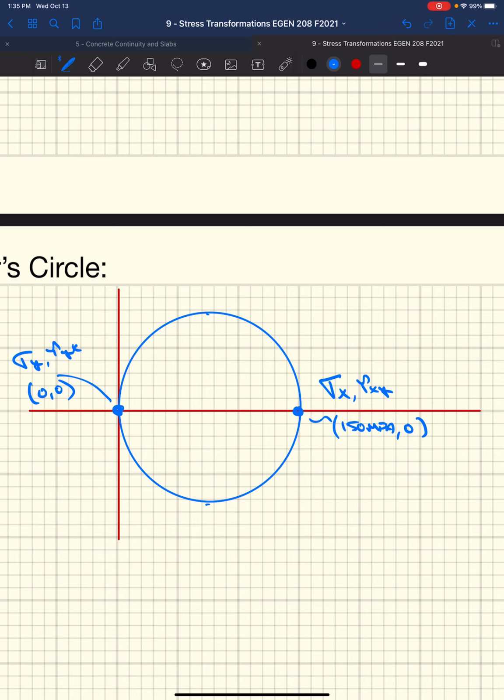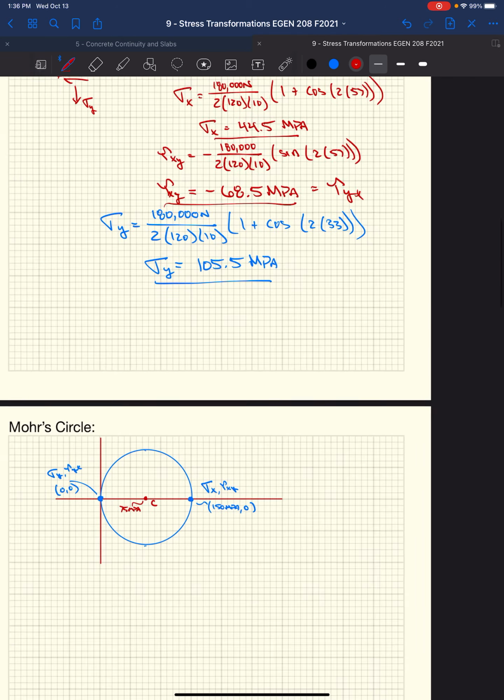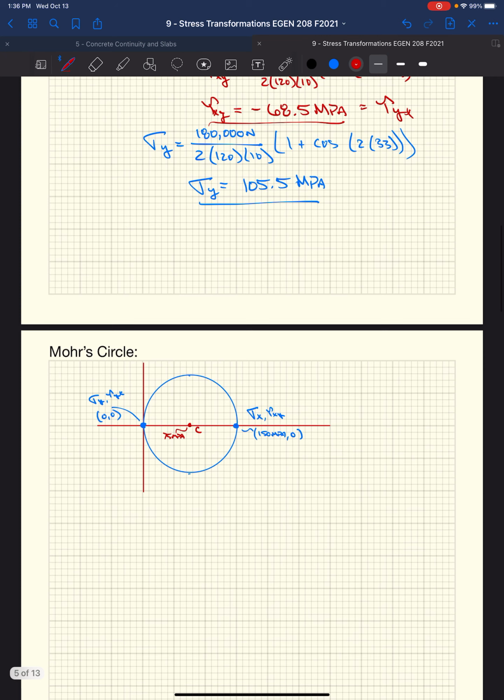All right, so we got our 2 points. We scribe a circle between those 2 points. The average of our normal stresses, that's our center. So that would be right here. That's C. Well, in this case, it's 75 megapascals. But if we wanted to figure out the actual equation for this, it's pretty easy in this case. But sometimes we've got these weird...